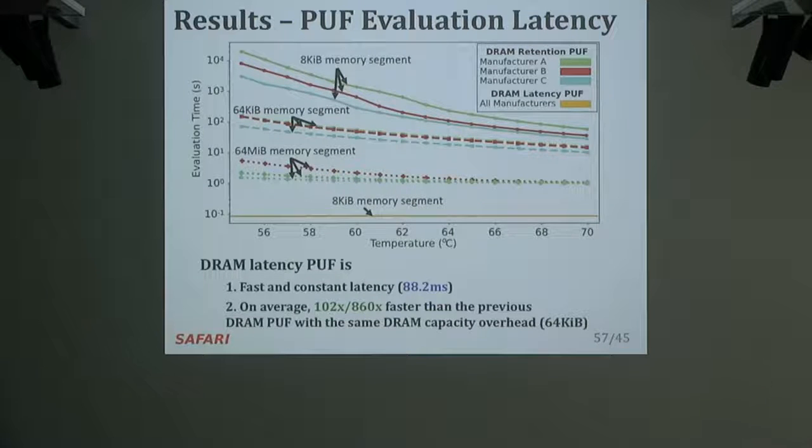Whereas latency is a different lever, right? You reduce the latency, which is fast. You're actually making the device faster. And it's actually giving you errors. And now you can mine those error patterns to generate random numbers or physical unclonable functions, whatever you want. I think that's the key realization. That's the fundamental realization. Playing with latency is much faster than playing with retention times.